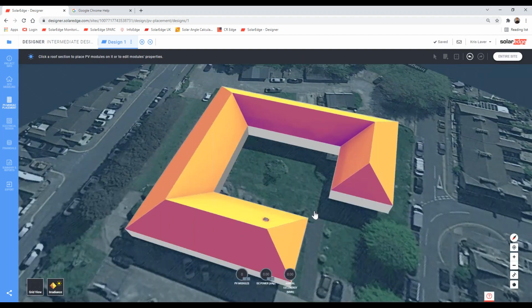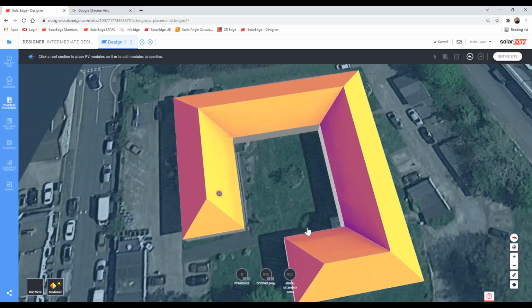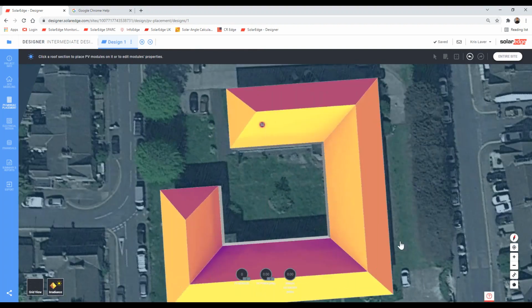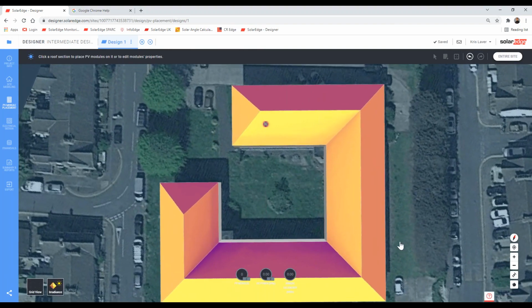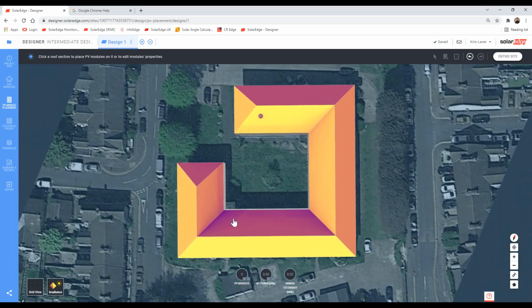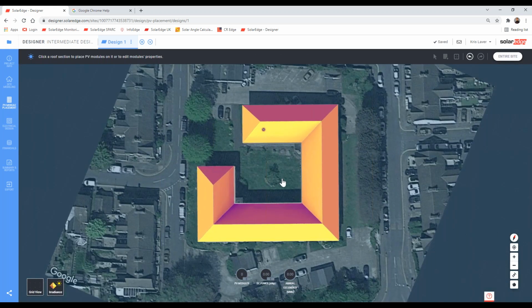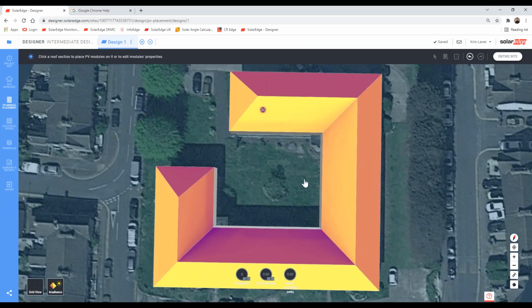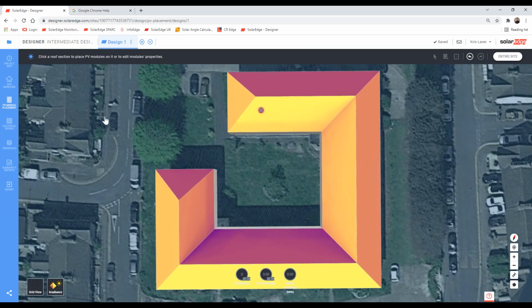Obviously, we're not afraid of the shade, and presuming everyone is aware of our concept of operation, shading is not something that vastly affects our arrays. We maintain a strict fixed string voltage, so the optimizers are essentially doing a juggling act to ensure that fixed string voltage reaches the inverter for optimum conversion from DC to AC. So just because it's shaded doesn't mean that you can't put modules there. It will only affect the module that's shaded. It will not affect the rest of the string. I'm sure we'll deal with that in more detail on a later webinar.